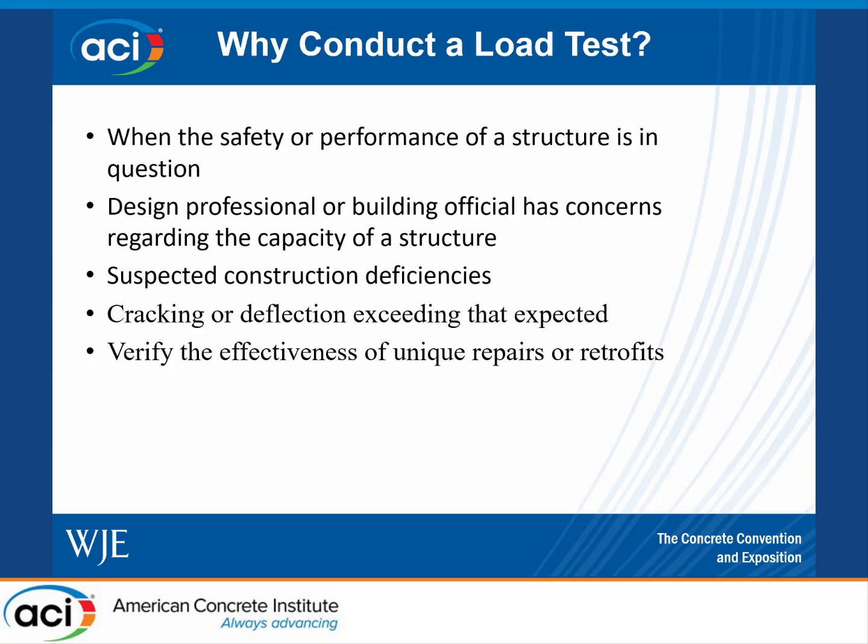Load testing is typically performed when the safety or performance of the structure is in question. A building department official or an engineer may have concerns regarding the capacity of a structure. There may be suspected construction deficiencies that may be difficult to resolve using other analysis or additional testing or non-destructive testing techniques. There may also be concerns regarding observed cracking or deflection. And also load tests are sometimes considered to confirm the effectiveness of unique repairs or retrofits that the building officials or other involved parties may not have experience with.